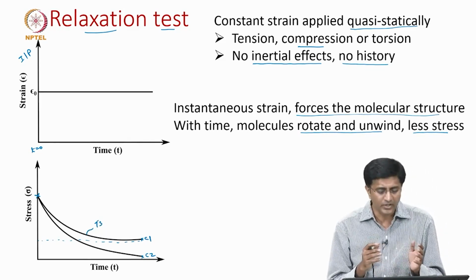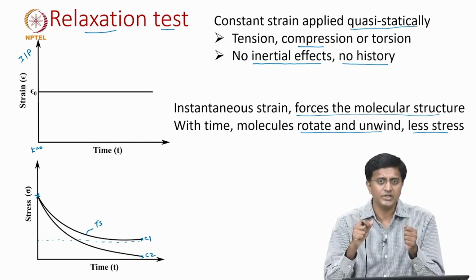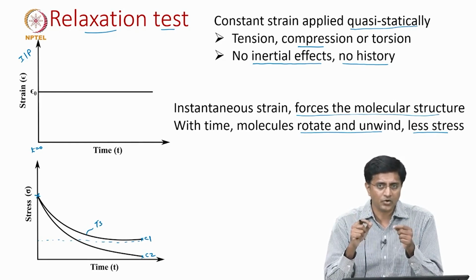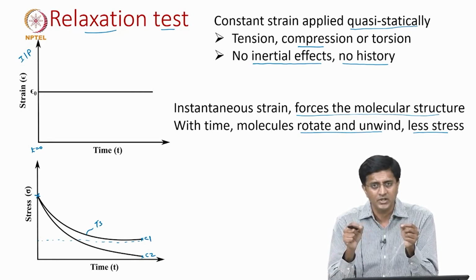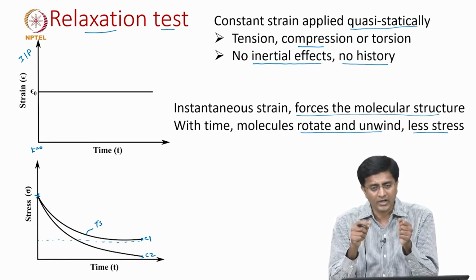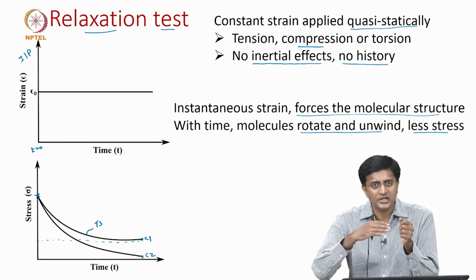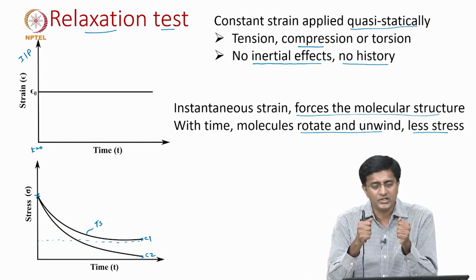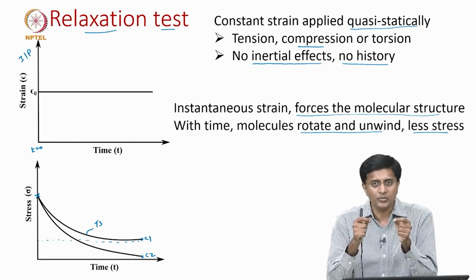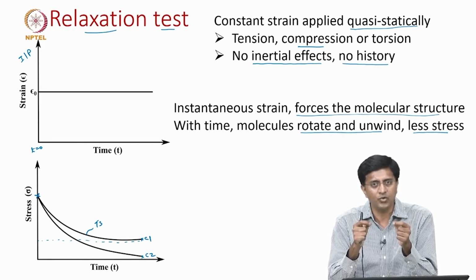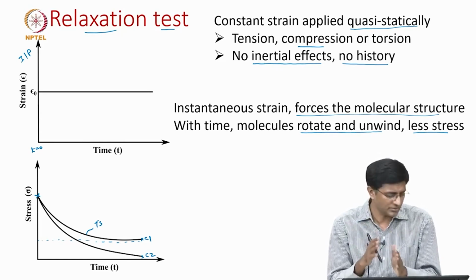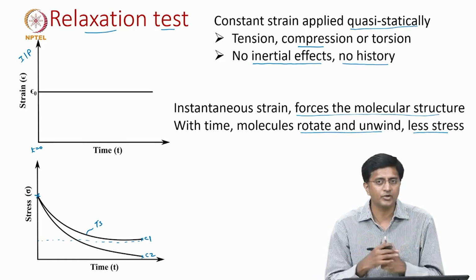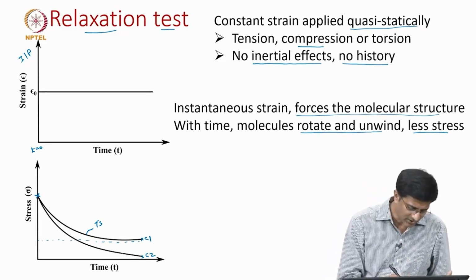will go to a position where, because thermosets, as we know, are a networked polymer, meaning there are cross links. So once we stretch, the stretch happens between these cross links, but then once you give time, these molecular chains are readjusting. Though they are readjusting, it is not like these polymer cross links can move. So because the cross links are limited in their movement, finally it settles down to a constant stress, even though you give an infinite amount of time. But for thermoplastics it is slightly different.